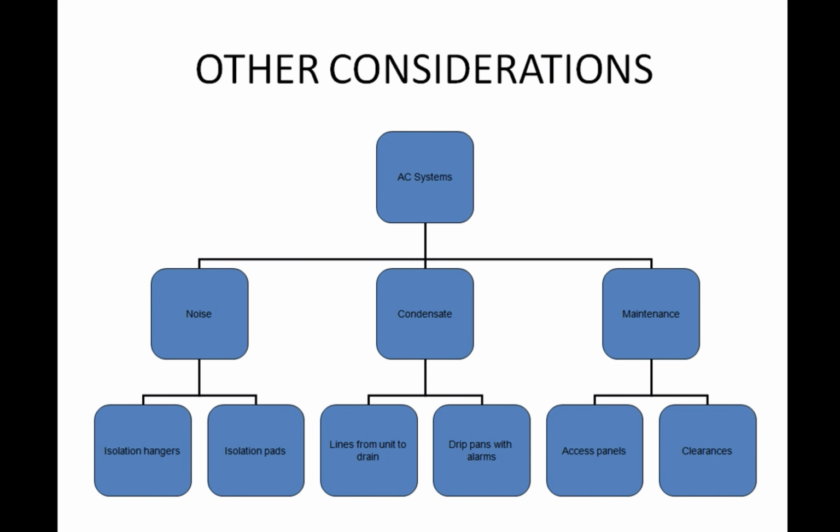All right, so in other considerations with your HVAC system, it's not simply an exercise in making sure that it doesn't fall down when it's installed, that it's hung properly, but these things have to be installed in a way such that you don't hear so much noise coming from the system. Like you don't have rattling against the Kindorf, rattling against the hangers that your vents or ducts are creating.